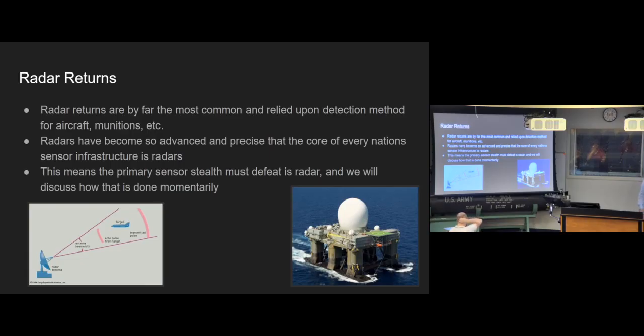Based on the time, since you know the speed of this wave traveling, you can immediately calculate the exact distance away. Then you can use tricks like the Doppler effect to calculate its speed. You can use the known position of the antenna, along with the phase angle of the return, to figure out its orientation. And then you can start doing a bunch of extra stuff. That's where signal processing comes into play.